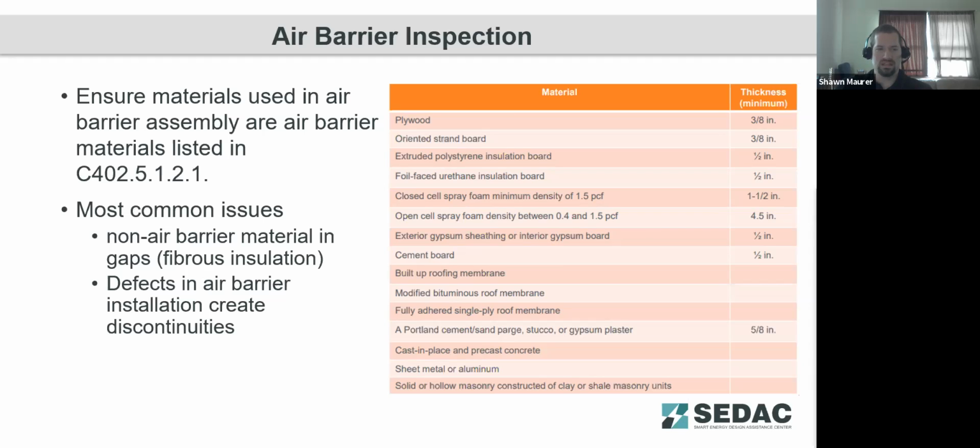Again, for most of these, the issue isn't necessarily the material itself, but joints between the materials, making sure that there is no air gap. If there is a joint, that there's adequate sealant there that is flexible enough that it's not going to dislodge or come apart.